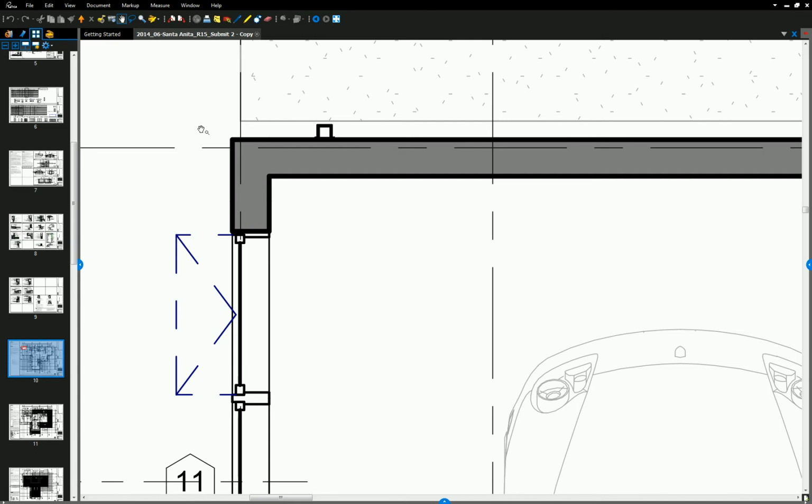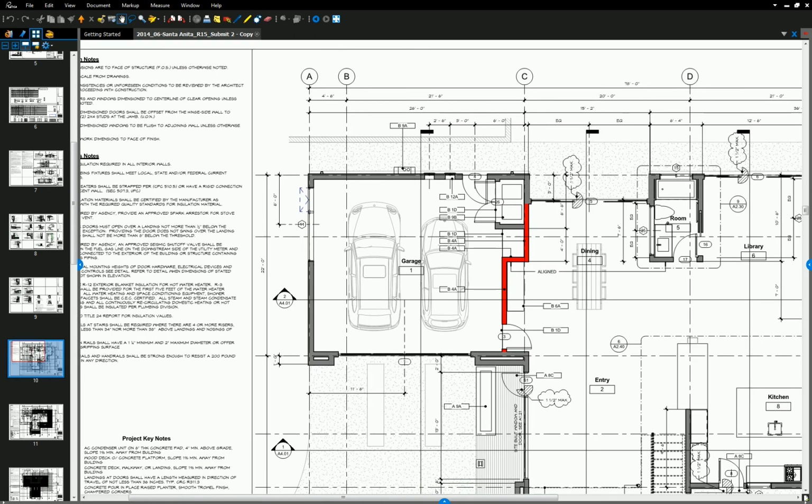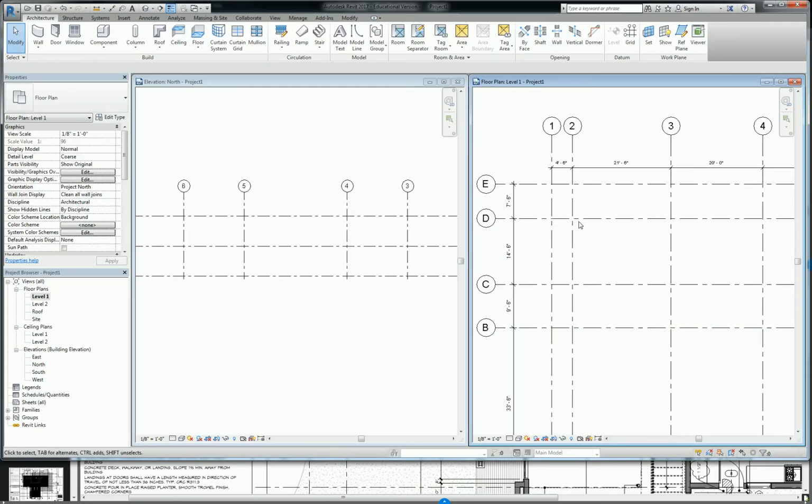So that's where, with type 5 construction, this is for your 147 people, that's where the grid lines go, if you're using grid lines at all. And if you dimension it, you're dimensioning it to the edge of stud, not the finish of the wall. So anyway, I want you to be aware of that, and when you go back into Revit, we're just going to do a quick schematic mock-up of that.